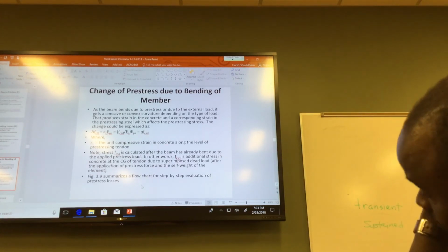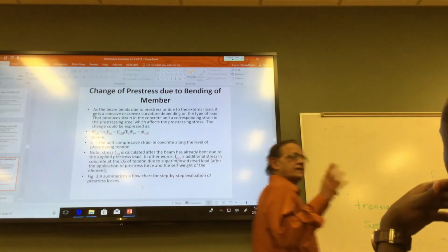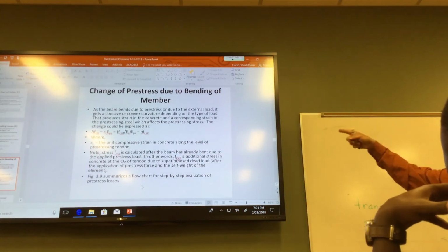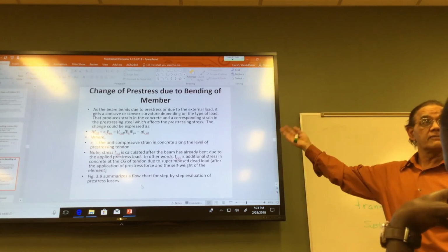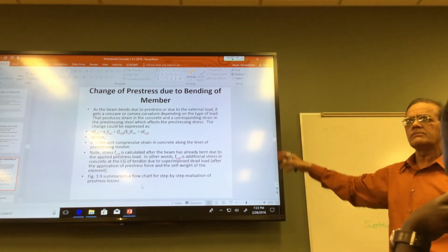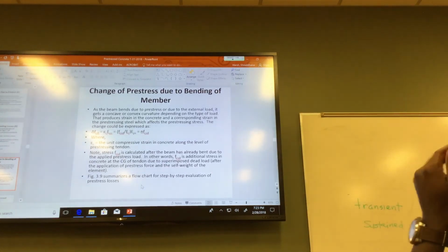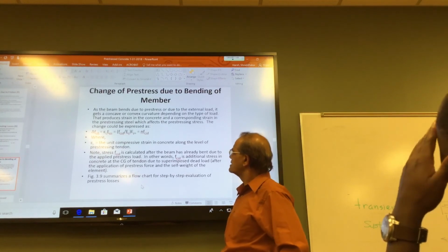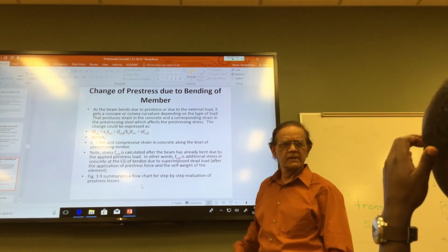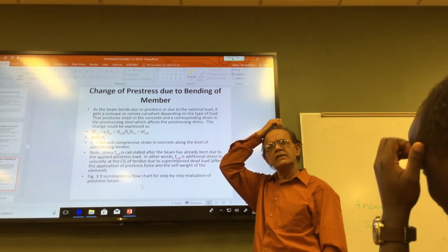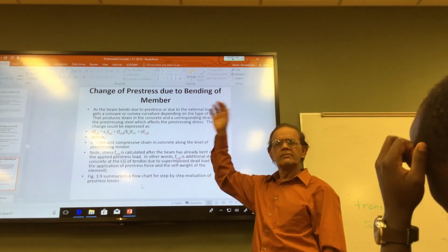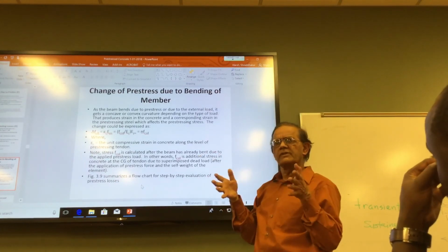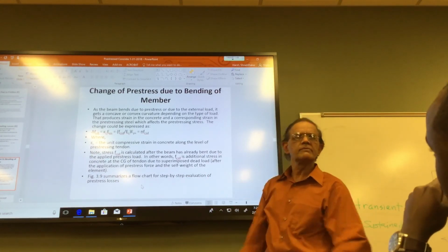All right. So I wanted to make sure. There are 3 items we have discussed: the anchorage seating, we talked about the friction, and then this is a negative loss. This is a positive. This increases somewhat. Is it significant anyway? No, it's not. It's considered because it is significant. It is not as much as creep and shrinkage, but it is still there. It's comparable to the anchorage seating loss, for example. Because that also has to do with strain, and this has to do with strain. So, okay.